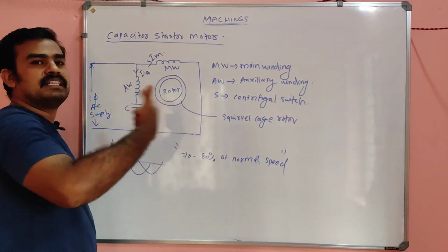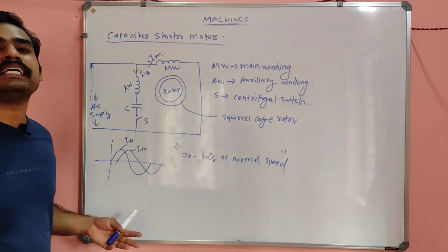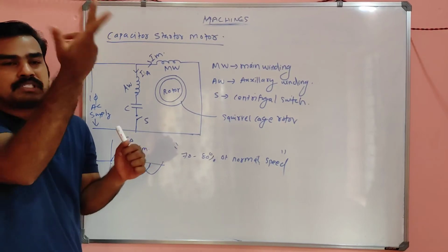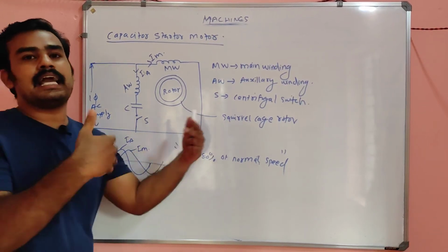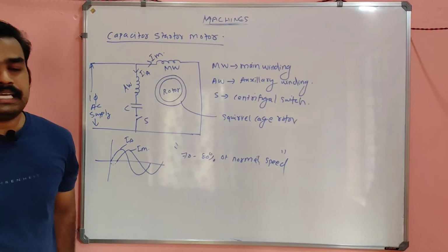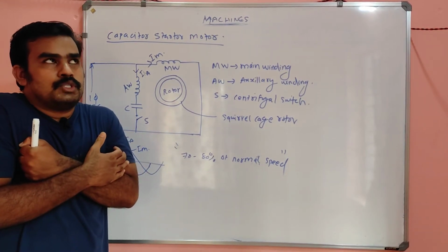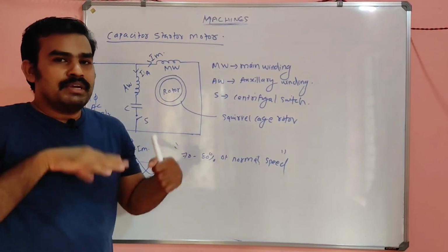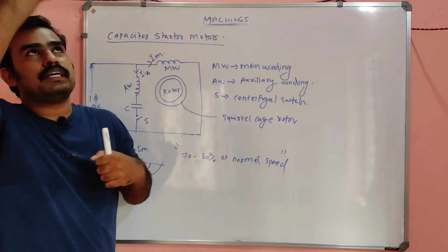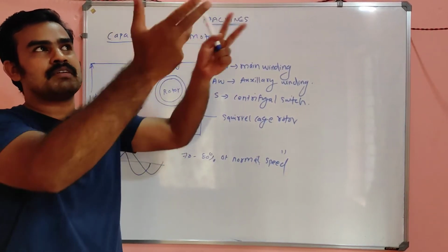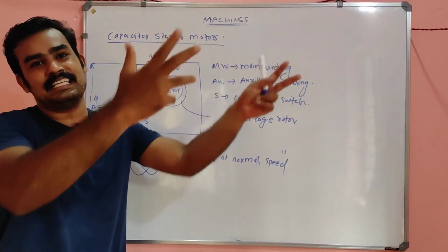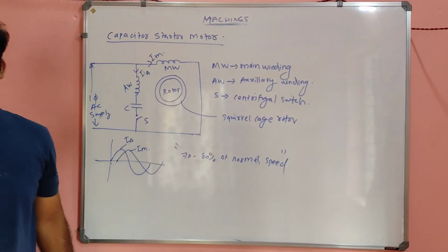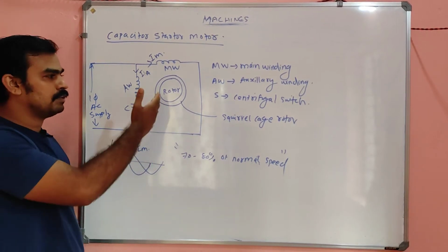Now the motor is running with some speed, overcoming all the inertia. Even if you change the polarity like north-south in a pulsating manner, it can catch up. Initially it was in inertia, so with north-south continuously changing, it can't respond. Now it is rotating at some speed, so even if it changes north-south, it can catch up to that north and that south easily. So the rotor will continuously rotate.